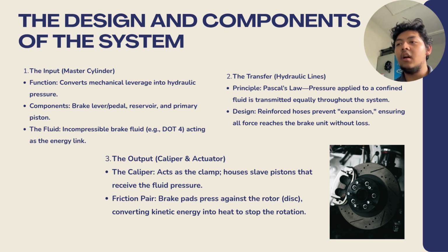Second, the transfer or hydraulic lines. The principle uses Pascal's law. Pressure applied to a confined fluid is transmitted equally throughout the system. The design uses reinforced hoses to prevent expansion, ensuring all force reaches the brake unit without loss.